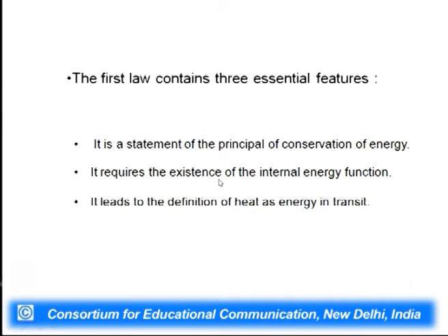So, the first law gives a definition of the internal energy function, and the last is the definition of heat. Heat is not energy as such, but heat is energy in transit. When there is a transfer of energy, that can be called heat, which induces disorderly motion in the system or surrounding.